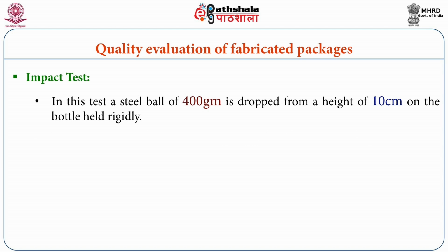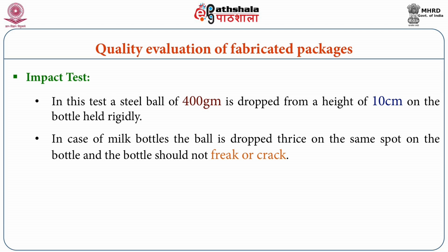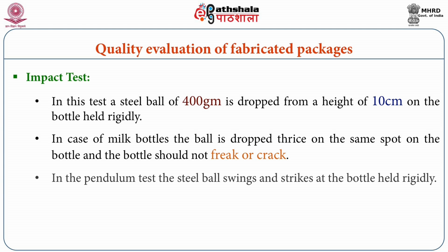In this test, a steel ball of 400 gram is dropped from a height of 10 centimeter on the bottle held rigidly. In case of milk bottles, the ball is dropped thrice on the same spot on the bottle, and the bottle should not break or crack. In the pendulum test, the steel ball swings and strikes at the bottle held rigidly. This is another type of impact test.